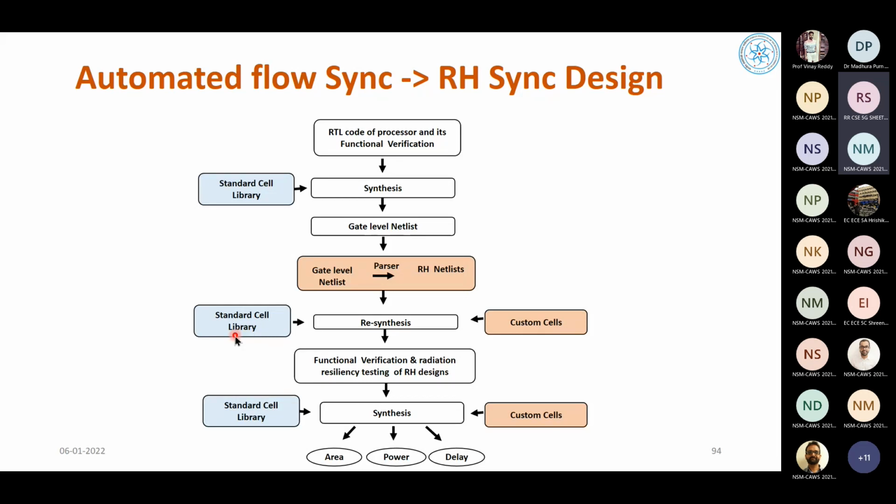Now, one important thing to keep in mind if you're using Design Compiler and working with ASIC design, one very important thing that is sometimes missed is that when DC reports power, this power is not always correct. You will get the correct value of power only when a switching activity file is added.